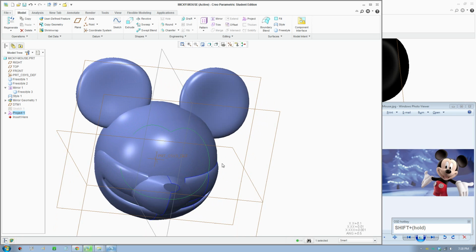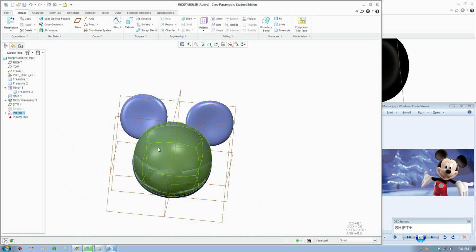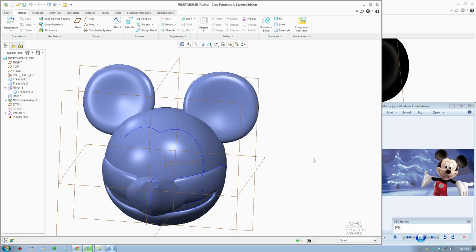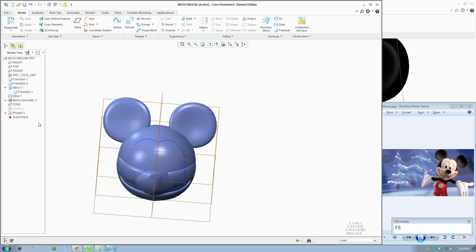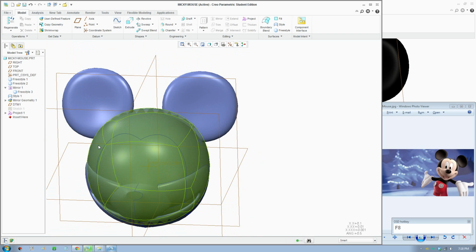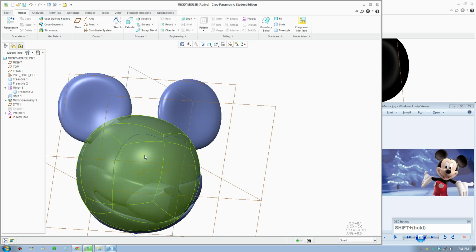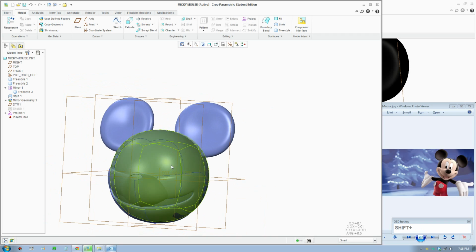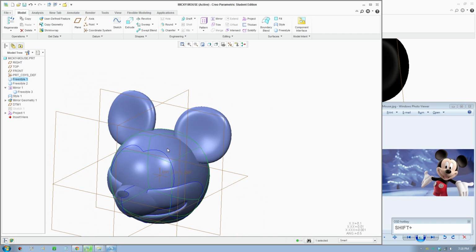Okay, for this step, okay, something's wrong. Okay, so there's missing line on the left here. We just do that again, so delete that. Okay, now it works. I just need to select the surface on the right. So make sure you select all the surface and create a projected line there. And now we can split this object by going to trim.